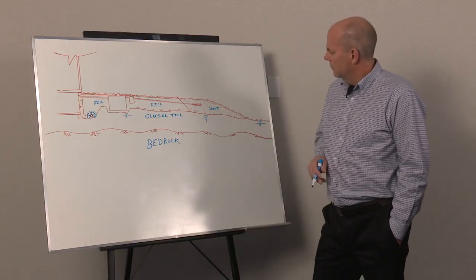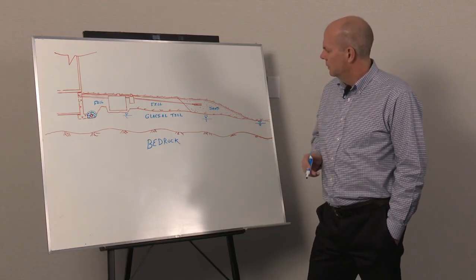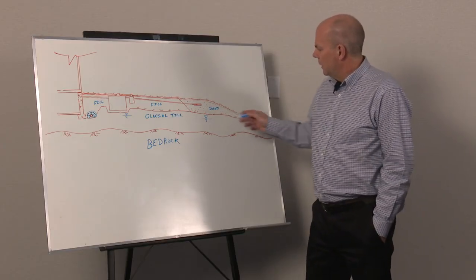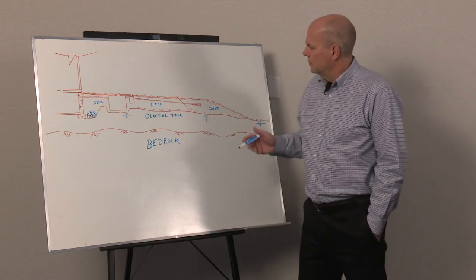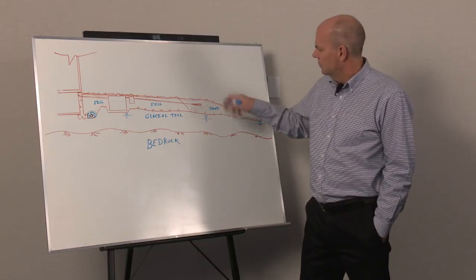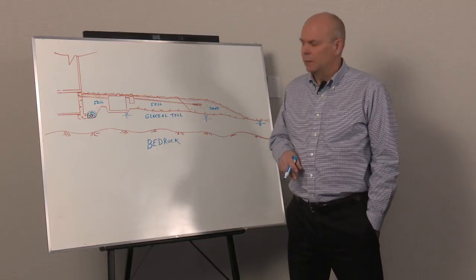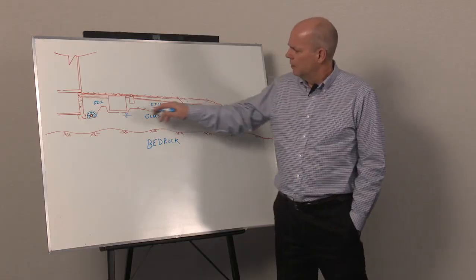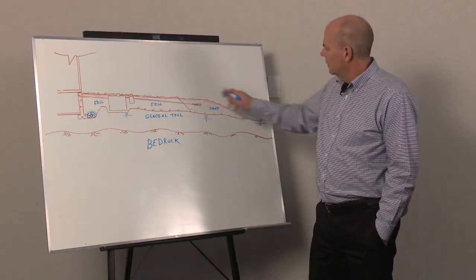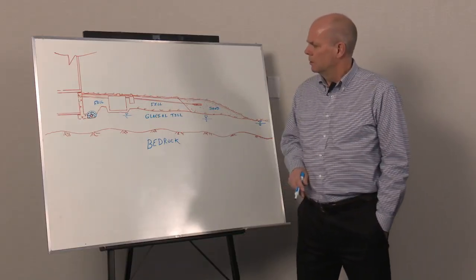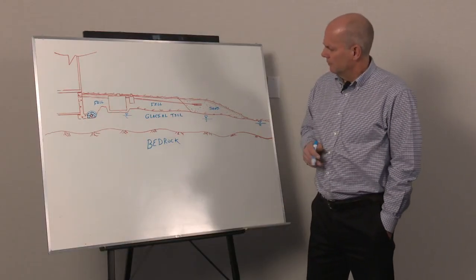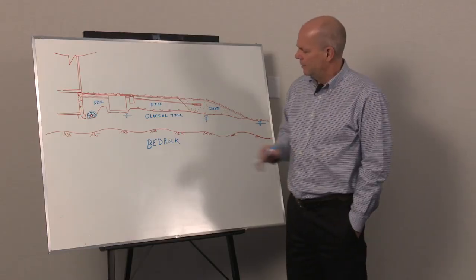One of the main components of the system is the sand bed, so we'll deal with each of these and how they behave. Most sites would have a groundwater table that's hopefully well below your ground surface in order to give you an effective sand bed. So in this case, our water table is down probably close to our foundation drain and not affecting the conditions up above. Okay, I'm going to talk about soil behavior, the various materials that I've identified here.